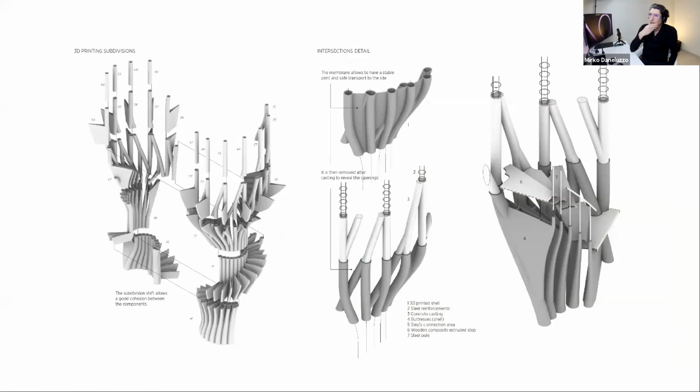Again, even here, we analyze the fabricability, or the way you can fabricate and manufacture the components, the pieces, aware now of the limitations of the technologies in terms of the size of the pieces that could be handled, especially in this case, because the idea for this tower is to build the pieces in a factory in a controlled environment, where you can also have quality control on the material. And then you just assemble the pieces on site.